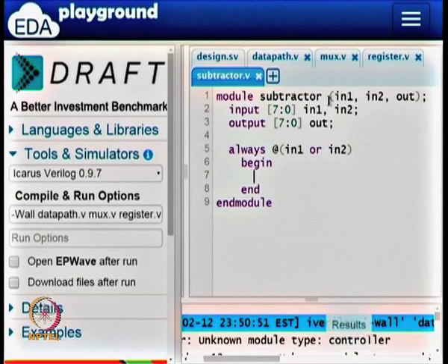And now I am going to show you something which is slightly different. I am going to write out as in1 minus in2. This is something that I have not introduced to you so far. I can do a design description for a subtractor very carefully, picking the basic gates, but Verilog also has what is called a behavioral description. In this case the behavior that we want is in1 minus in2. This minus stands for subtraction.